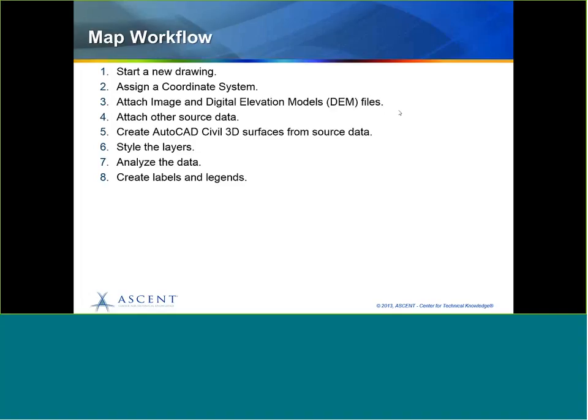This becomes so huge when we're talking about reducing the budget of a project. Let's say I have a project where I need to minimize the cost of building roads, and so I can actually attach a GIS data coverage of our road center lines and then also our parcels, and I can perform a query right in the software to say, hey, show me all of the parcels that are within 100 feet of a road that is a major arterial road.